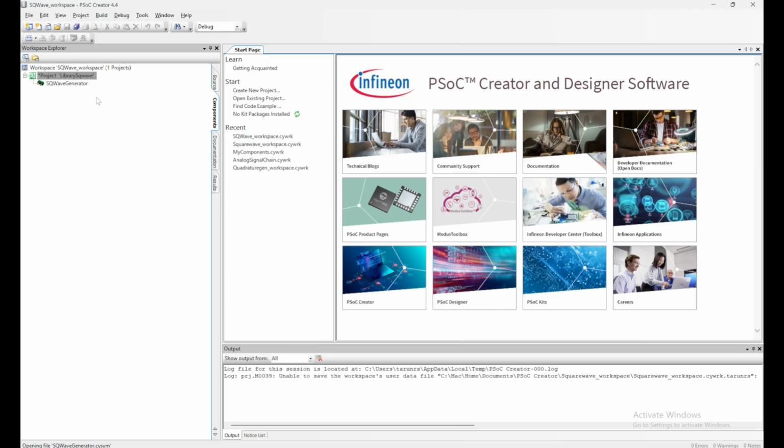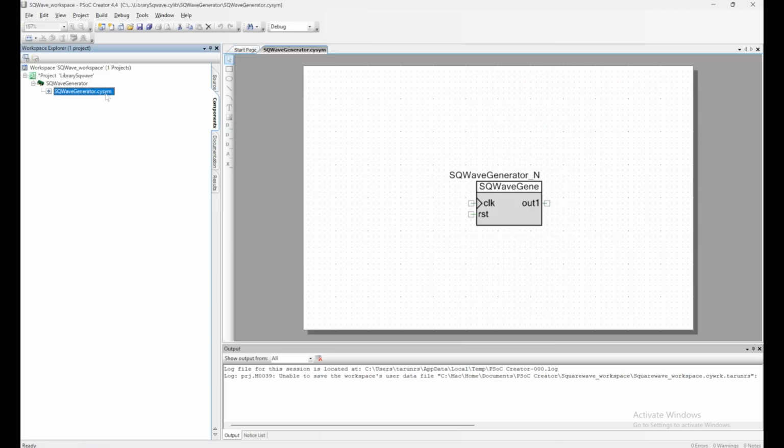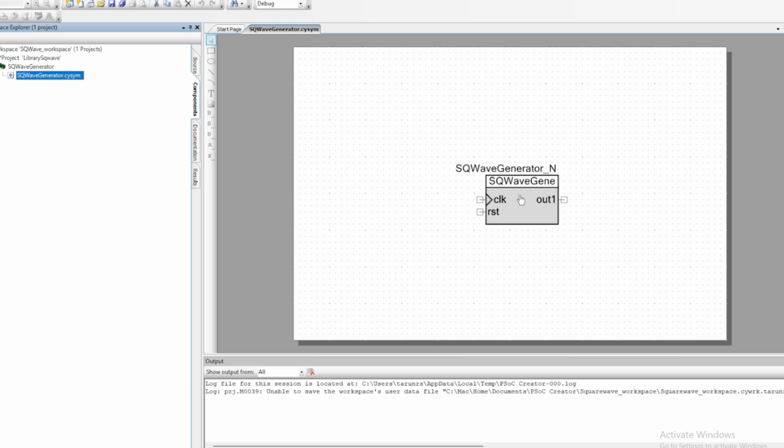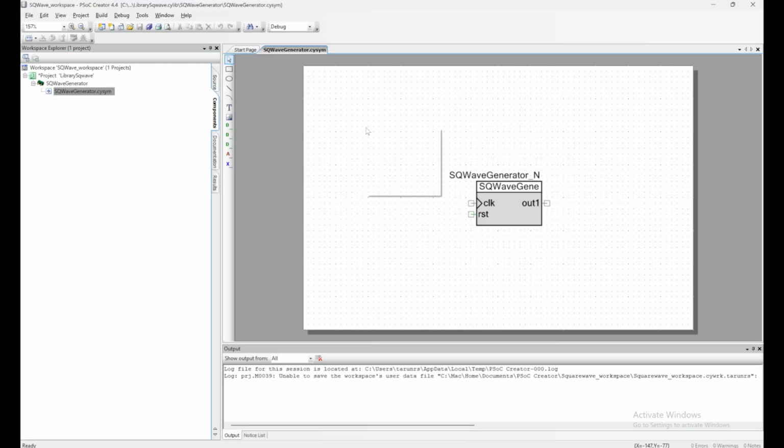Once the symbol file has been generated, we can edit the symbol if we want in order to change the layout of the present terminals. After editing, we can start with the logic behind the component. So we generate a Verilog file which will support the component's backend. In order to create the Verilog file, we right click on the symbol file and click on generate Verilog.